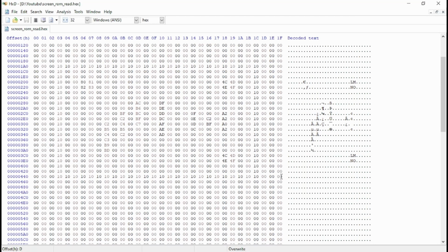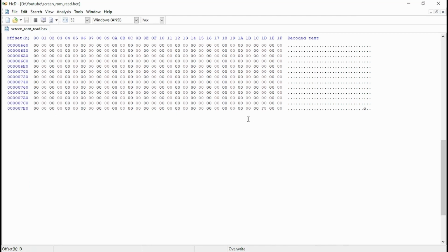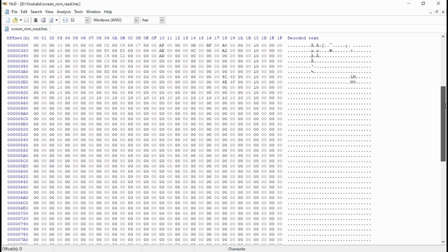Now don't forget, this is a little misleading. Remember the memory map? The ROM goes from 000 to 7FF, but it will be sitting in the memory location of F800 to FFFF. Actually, we saw it 16 times in the upper 32K. So when we're looking at the hex file, we need to think about converting the location in our heads from 000 to F800, and so on for higher addresses.